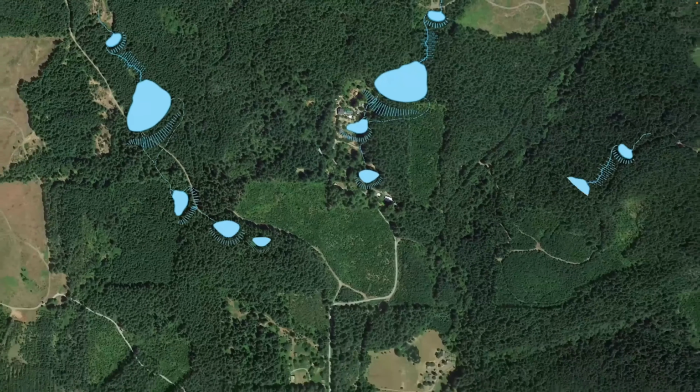One thing to consider for soil test pits is how many test pits you want to put in for a given pond. You probably want to put in a few because you're wanting to look at the entire basin. A few test pits at the dam site and a few back from the dam could be a good decision. You get your preliminary test back, and hopefully these tests really show that you are good to go for construction.